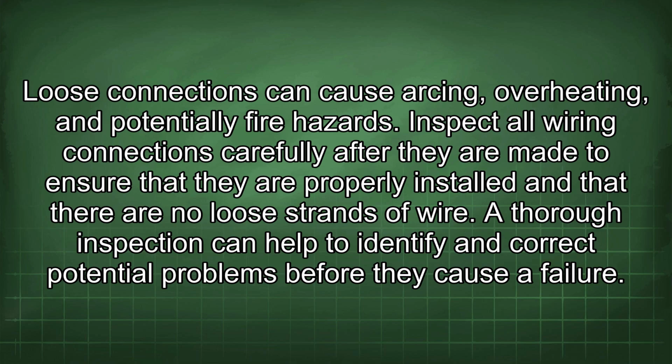Inspect all wiring connections carefully after they are made to ensure that they are properly installed and that there are no loose strands of wire. A thorough inspection can help to identify and correct potential problems before they cause a failure.